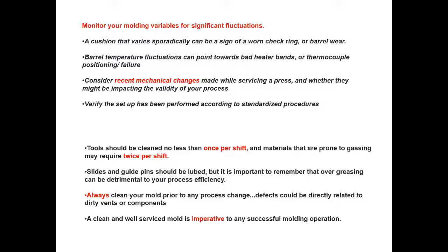And anytime you make a process change, before you make a change, you're always going to clean the mold first. Defects could be directly related to dirty vents or components. And as we said before, a clean and well-serviced mold is imperative to any successful molding operation.